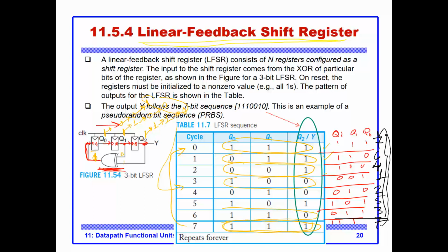Okay, so the other thing that we notice here, since I have 3 flip-flops, is it not reasonable to expect that I'm going to have 2 to the 3 codes, which means 8? But if I count those sequence, I'll get 1, 2, 3, 4, 5, just 7 codes. I have just 7 codes here. So the number of codes here is 7. Why not 8? Okay, two points about the length of the sequence.